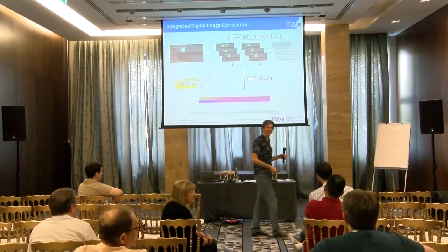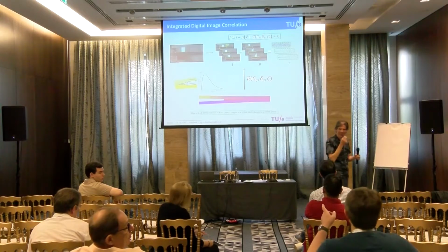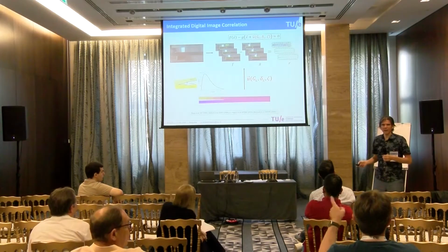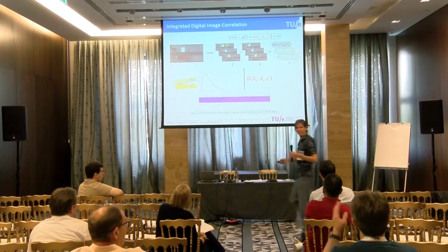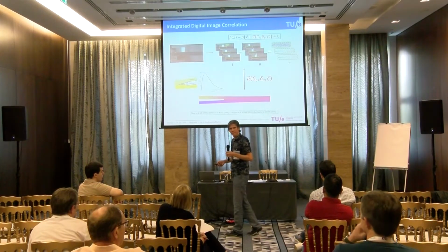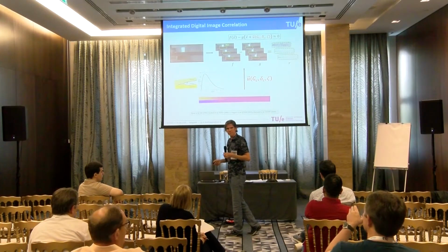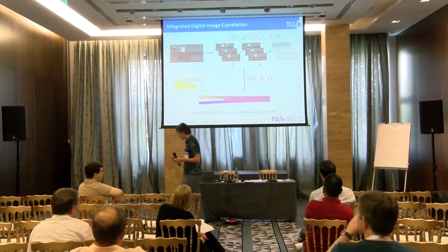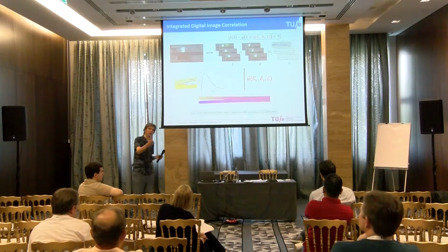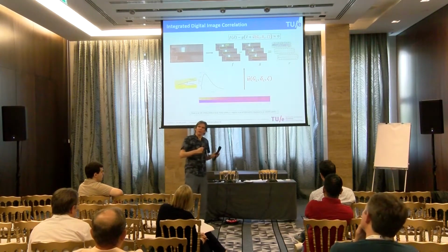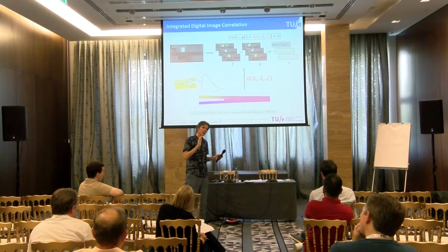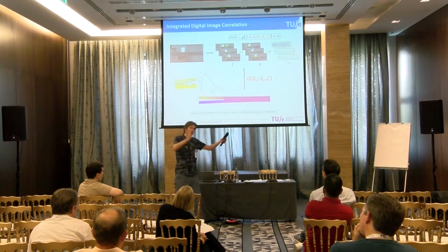About halfway through the presentation, you showed some traction curves for different mixed mode ratios. For the lower mode mixities they showed distinct peaks, and for the higher mode mixity, I think it was 70%, it was sort of flat. What that means is that we never reached the stable crack growth regime, because basically everything was process zone there.